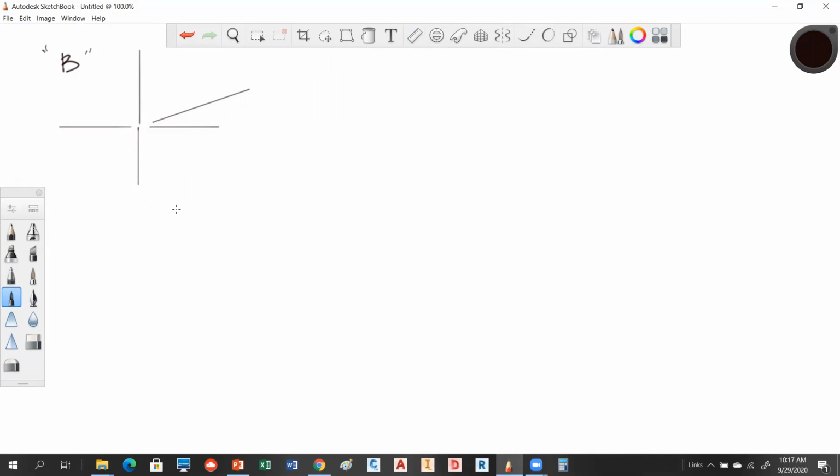Okay, this right here is member BC. What did we resolve BC to be? Wasn't that 0? Okay. We have an external load here of 8 kips, right? What did we solve AB to be? We solved that as a compression member, wasn't it? Did AB turn out to be compression? Okay, so that means he's coming in on the joint like this, right? The joint's in compression, and that was 21 kips, right? Is that correct? Okay.